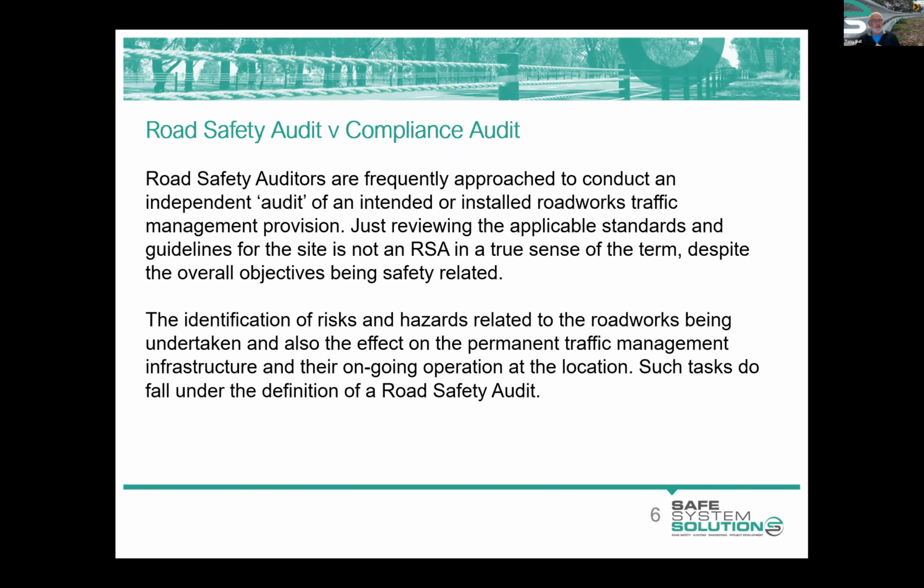Yes, you would identify that through a compliance audit, but the road safety audit will also look at other items of safety that could be part of what has been introduced through that temporary traffic management arrangement. So it's all about making sure that all the risks and hazards have been looked at. Have they been managed? Have they been mitigated? Have they been removed? All of those things through the hierarchy of control.